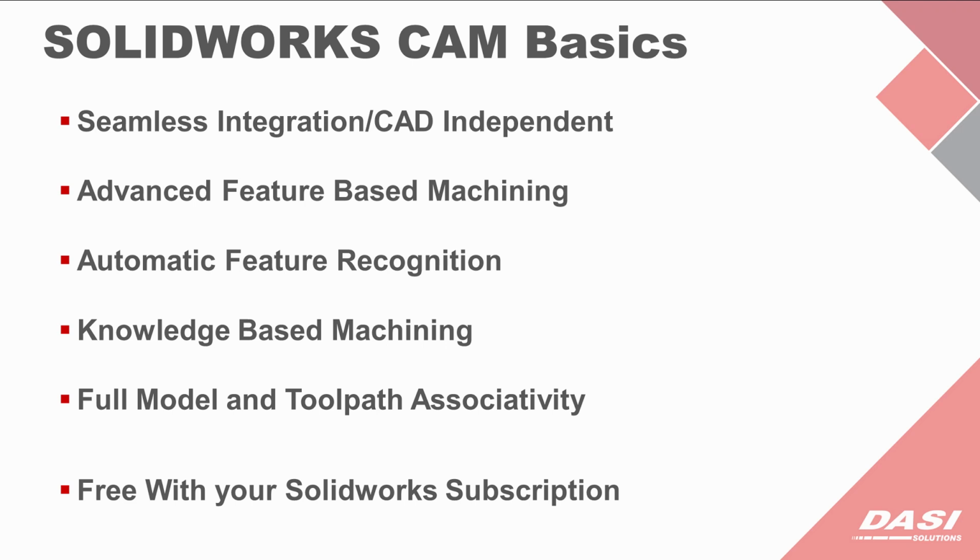The extra nice thing about that knowledge-based machining is that all of the strategies and all of the processes developed over time can be customized to suit your machining practices. So basically what you do is you end up teaching SOLIDWORKS CAM how you like your parts to be machined and what your machining processes are, and it can get smarter and allows you to get your models from model to program to reality much quicker.